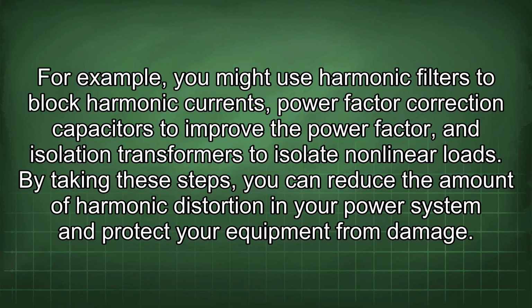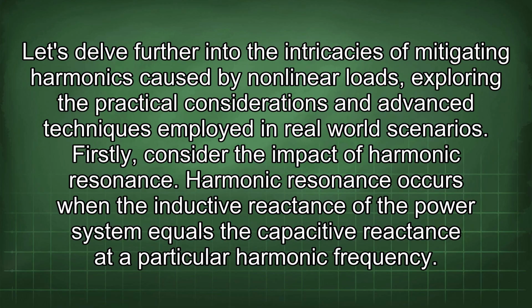For example, you might use harmonic filters to block harmonic currents, power factor correction capacitors to improve the power factor, and isolation transformers to isolate nonlinear loads. By taking these steps, you can reduce the amount of harmonic distortion in your power system and protect your equipment from damage. Let's delve further into the intricacies of mitigating harmonics caused by nonlinear loads, exploring the practical considerations and advanced techniques employed in real-world scenarios.